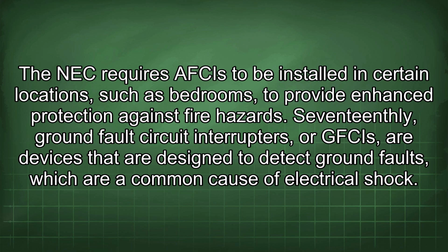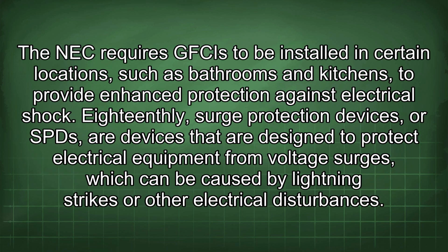protection against fire hazards. 17thly, ground fault circuit interrupters, or GFCIs, are devices that are designed to detect ground faults, which are a common cause of electrical shock. The NEC requires GFCIs to be installed in certain locations, such as bathrooms and kitchens, to provide enhanced protection against